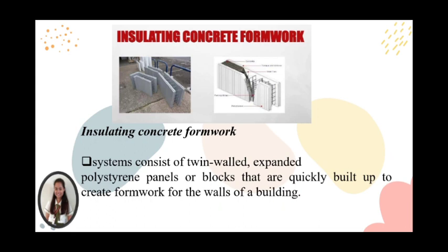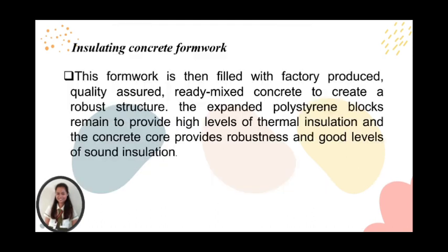Next on the list is the insulating concrete formwork. It is a simple construction system using purpose-made insulating panels or blocks as the formwork for in-situ concrete. Once the concrete has been poured, the panels remain in place to act as thermal insulation. There are a variety of different block and panel systems, using typically either expanded polystyrene insulation or extruded polystyrene.